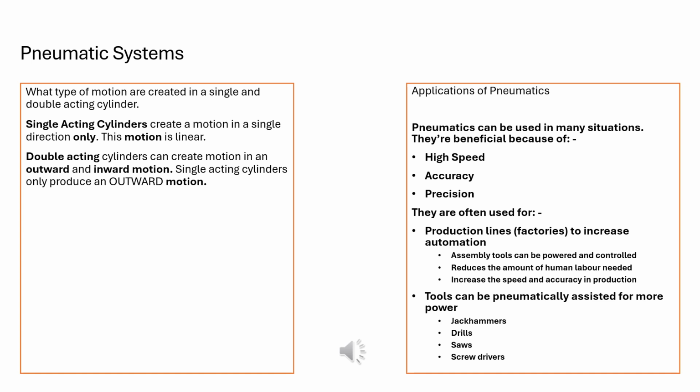So all of these things need to be considered in your answers, but always think about the scenario you've been given and how that applies. Whenever you need high speed, accuracy or precision, you're really going to go down the route of pneumatics. Remember that with hydraulics, you do have the risk of working with fluids and working with oils. So there is going to be an element of maintenance to consider there.